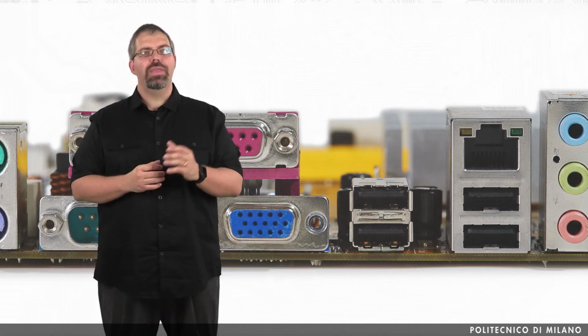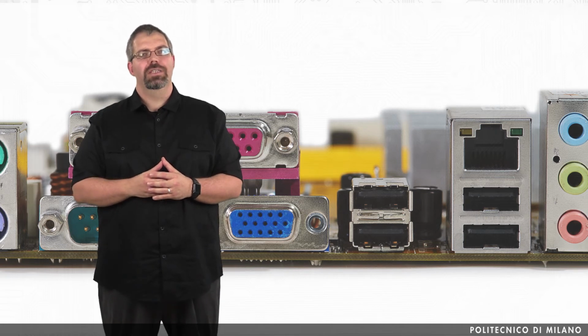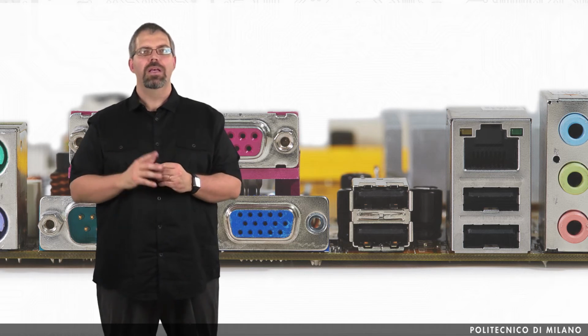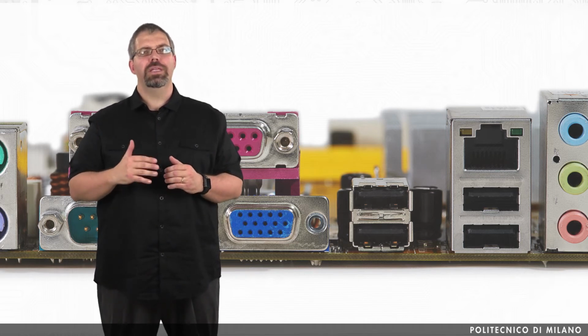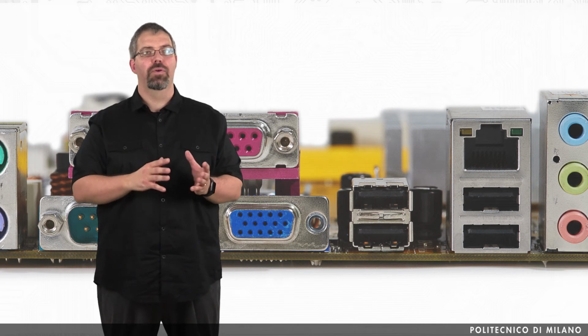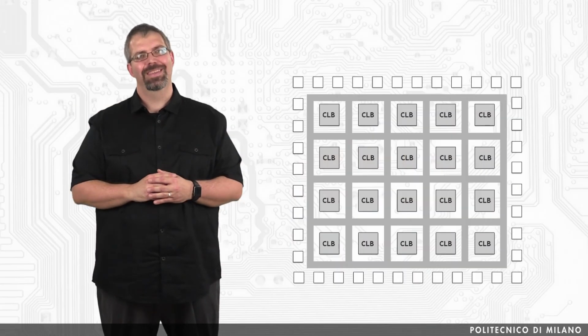Now, one other thing which is quite interesting to be noticed is that the I/O pin will be physically bound with external components by the board vendor. Therefore, whenever you are going to be interested in using a certain board instead of another one, please be careful in checking the connectivity before implementing your design.